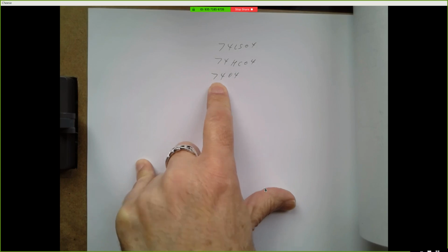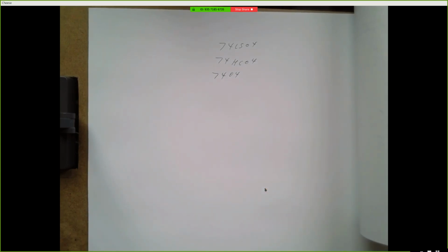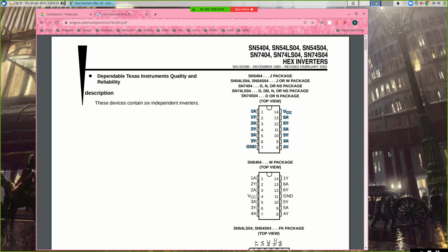And the mil-spec devices, they can handle more vibration, they can operate at a higher or lower temperature, they can handle higher humidity. They're made to be more rugged. They're things that you would put into space, for example. And they have a different pinout, right? In particular, the ground goes over here and VCC goes over here.